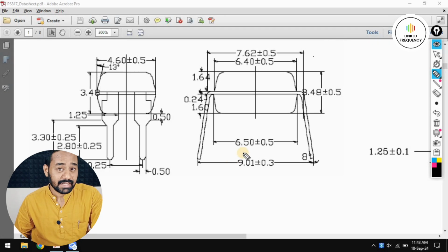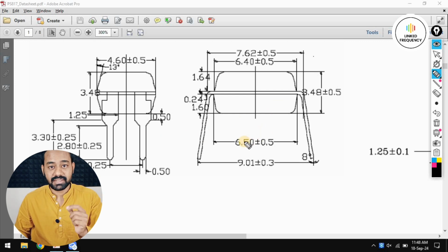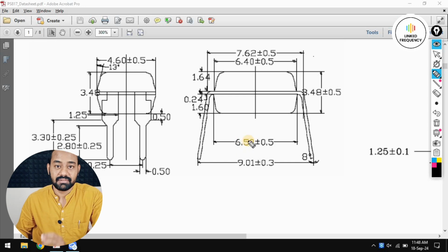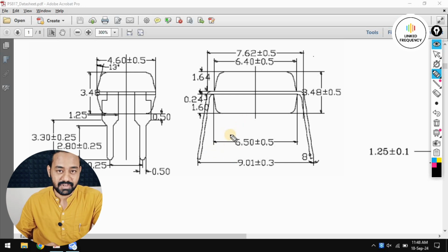Here we can see that the total distance from one pin to another pin, vertically and horizontally, is given. Now using this data, we can create the Cartesian geometry data in our PCB footprint design. It's absolutely the same as our 555 timer IC's design. I think if you have understood that part, this part is quite easy for you. But still, I'm going to explain it the first time.